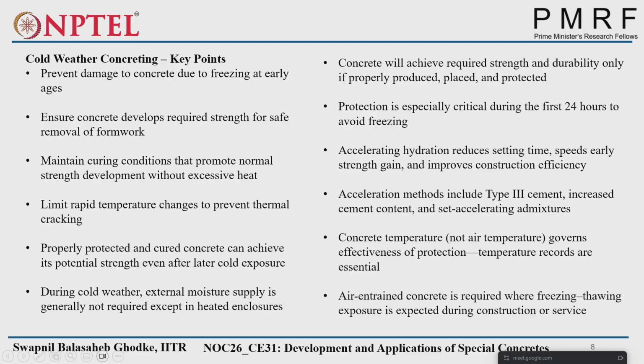Then accelerated hydration reduces setting time, speeds early strength gain, and improves construction efficiency. So accelerating hydration is most of the time used in cold weather conditions to get early strength gain and remove the formwork as early as possible. Because if we go with normal conditions, the construction will take a very long period, and the cost will increase, right? So we have to also consider that aspect.